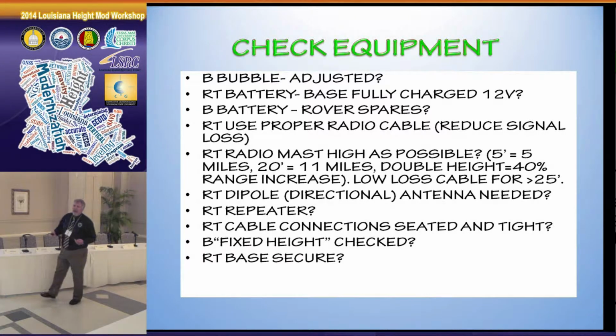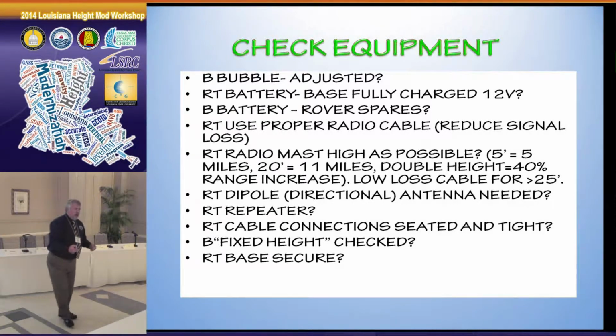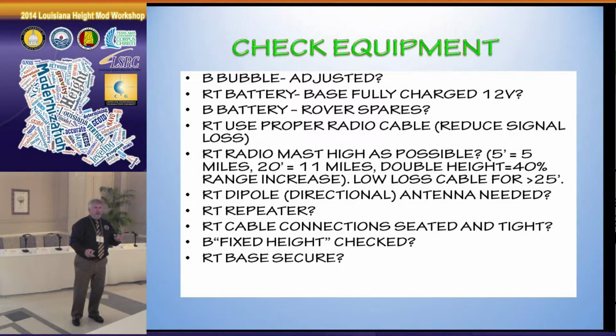Check your fixed height once, at least, in each campaign. Your point wears, that could be 1 millimeter, 2 millimeters, 3 millimeters, I don't know. And then sometimes with a base station where it says 2.0 meters with a dowel that you slide through that hole, and you set your legs up, and you actually measure that height. You probably aren't going to have 2.00 meters. You're going to have several millimeters different. It's going to be a little bit more or less.